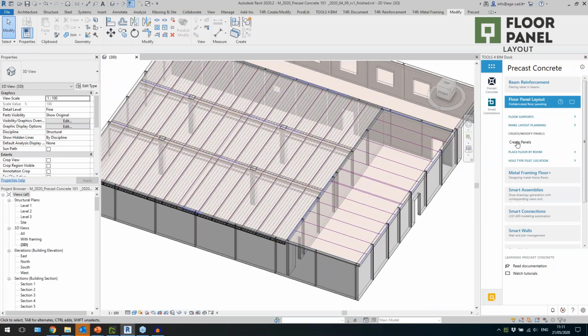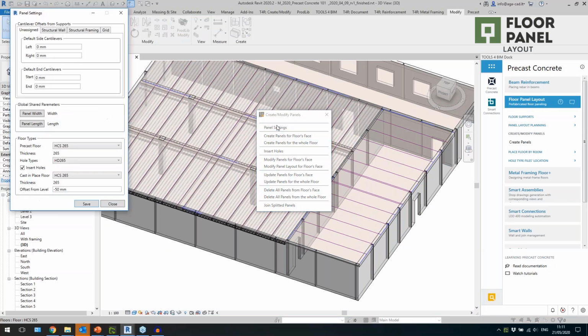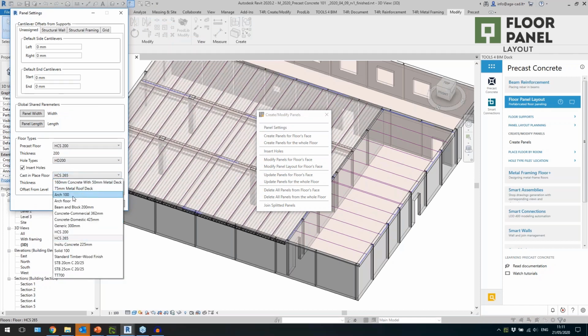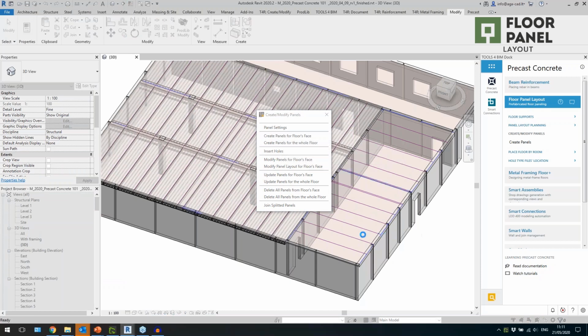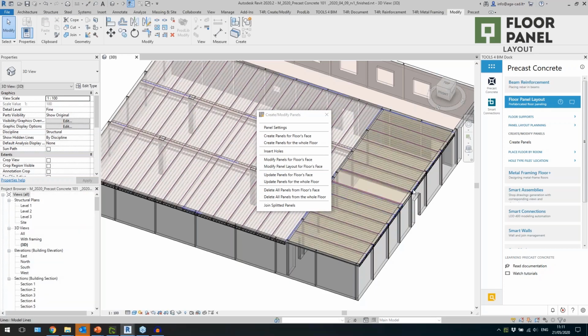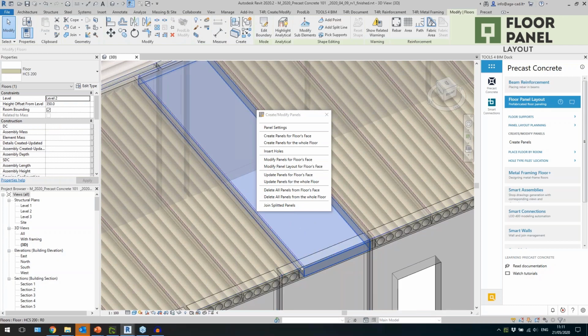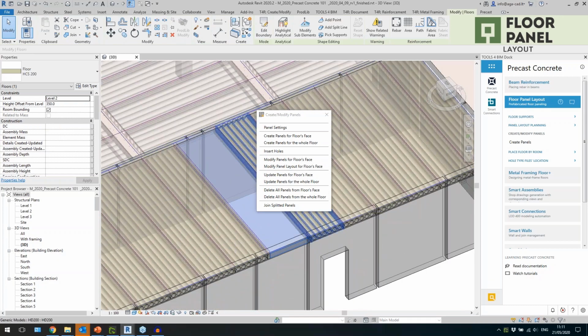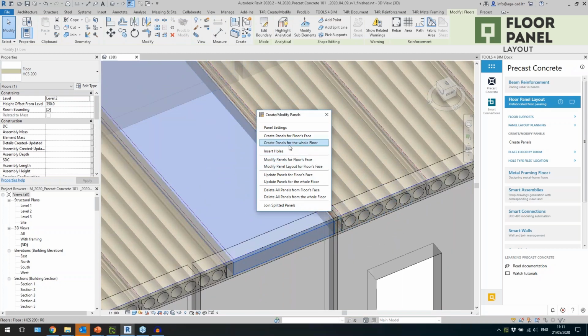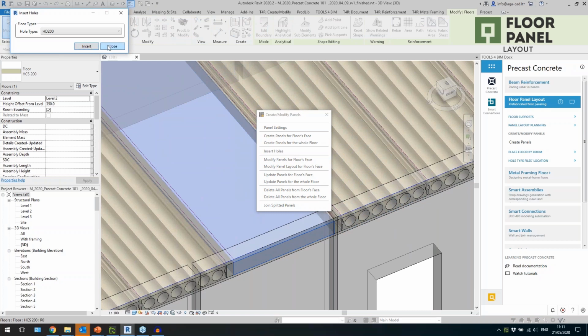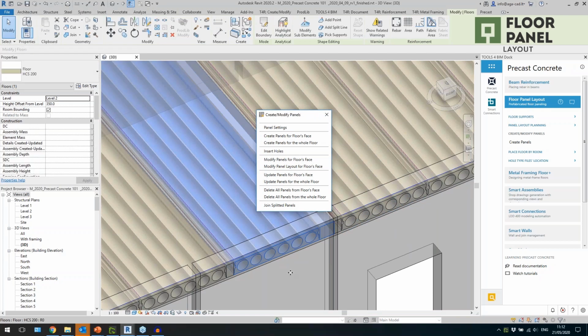Yeah, and depends what kind of settings I use. My slab will be like that, right? For example, I'm gonna change this to another one. So I'll do that and do this for the face this time. Like that. And the size of this floor, which is not standard size, it will be different floor type without holes, but later on you can modify it or insert additional cuts if you have a family that you need.